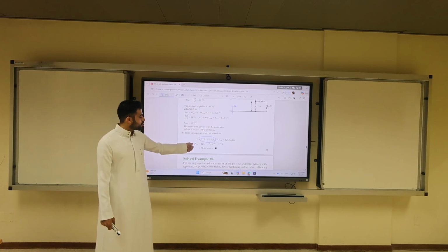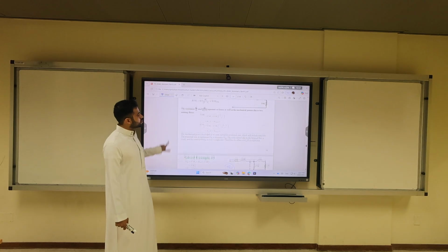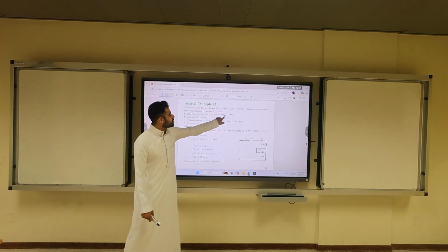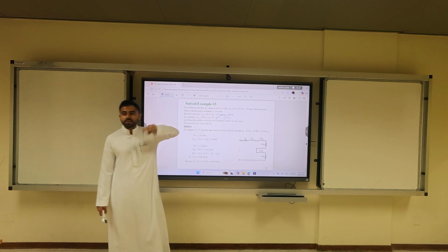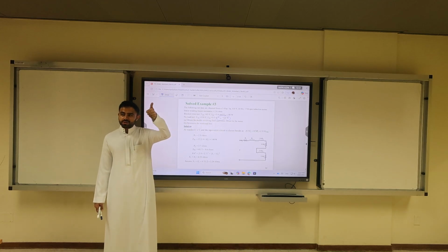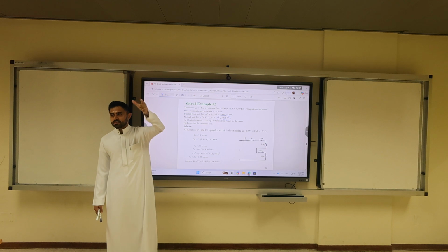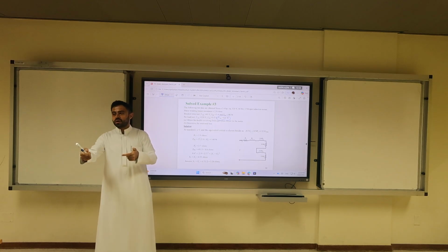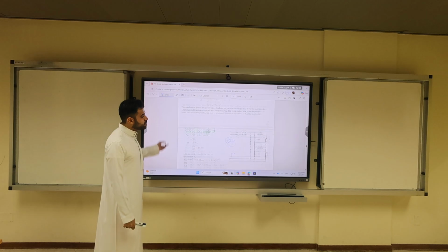From which test? The no load test, the 125. So no load power is copper losses plus rotational loss. If you subtract the rotational losses from P converted, you get your final output power. And this is a very inefficient machine.